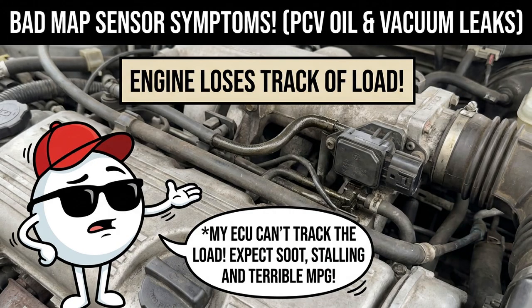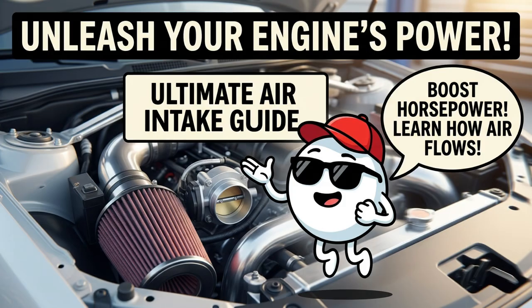When a MAP sensor gets clogged with PCV oil vapor or experiences vacuum hose leaks, the ECU loses track of engine load. The vehicle enters a restrictive backup mode, resulting in heavy exhaust soot, sudden engine stalling under load, and awful fuel economy. Once air passes the intake filter and airflow sensors, it meets the primary gatekeeper of engine speed,